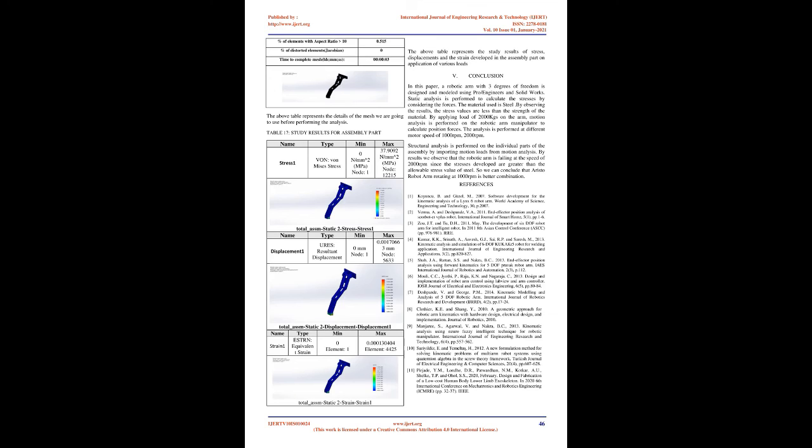Once the loads from motion analysis are obtained, we perform structural analysis on each modeled part of the Aristo arm and determine loads, stress, and strain for each part. The following selections are made for all the components at the beginning of our analysis. 1. Select Add in Simulation. 2. Select Simulation, import motion loads. 3. Select parts to import motion loads: first, second, third, and fourth. Enter frame No. 4. Material: steel.